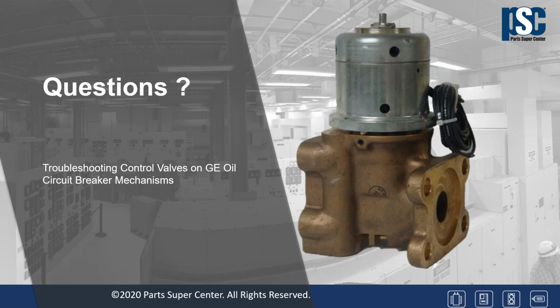Not sure where it has come from, but most of the time, if it is clogged, you will find rust in there that has come from the air receivers. So you want to make sure that you bleed down your air receivers on a regular basis using the sump at the bottom of most mechanism cabinets.